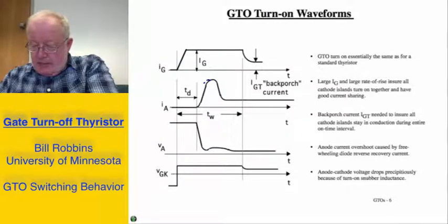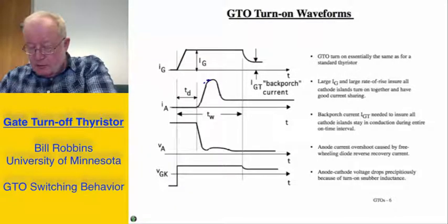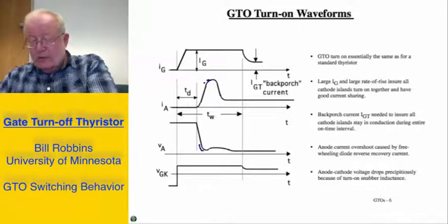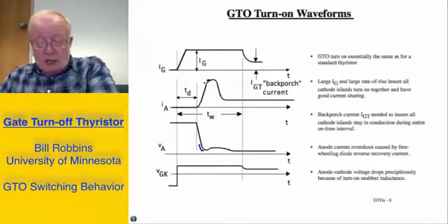At the time the freewheeling diode current reaches its reverse maximum, the rate of change of the anode current is then much less than it is in this steeper portion, and so the inductance is no longer effective, and we still have some finite voltage larger than the on-state voltage in the anode-to-cathode voltage.